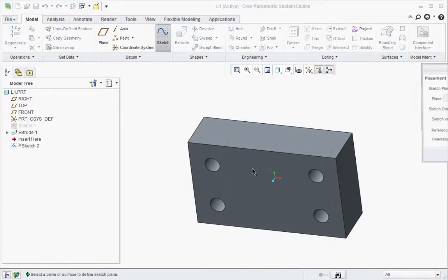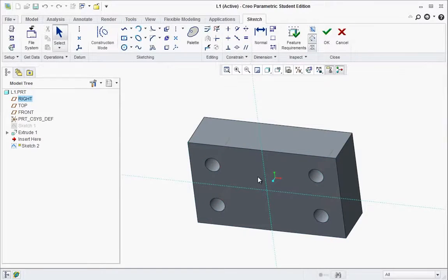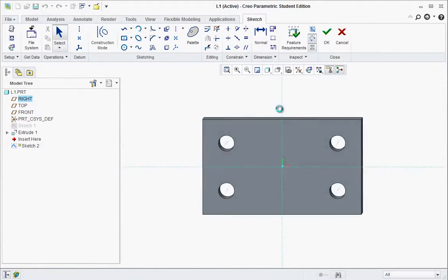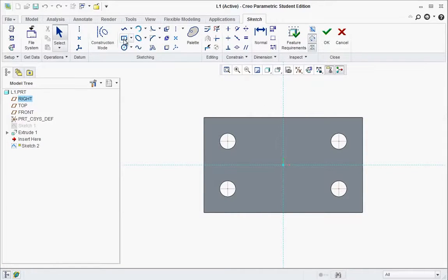Now we could start another sketch on the front face of this. And I'm going to go to AB front. And again, we could use our center rectangle tool to draw this out. Now notice we're not capturing the edge again. Remember the trick to that. Drag it close to it, a little bit distance away, then middle click a couple times.